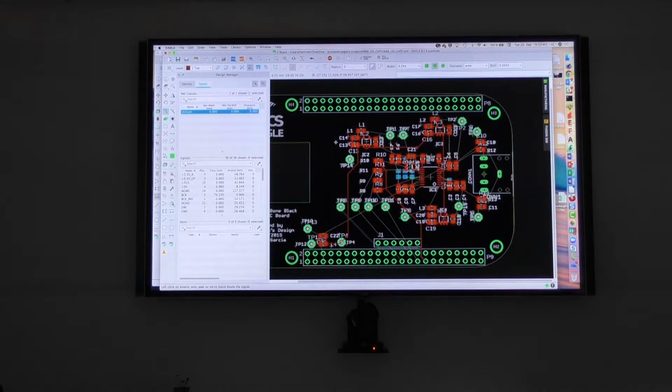But yeah, people are doing this. If you combine it, you do your stuff before you start out, because then I have what I want, and all the unimportant things I leave to the autorouter. I was kind of doing it the other way when I was experimenting with it, because I knew that I wanted to route all my power by hand, but I was still at the stage where I was trying to move components around to the best placement.